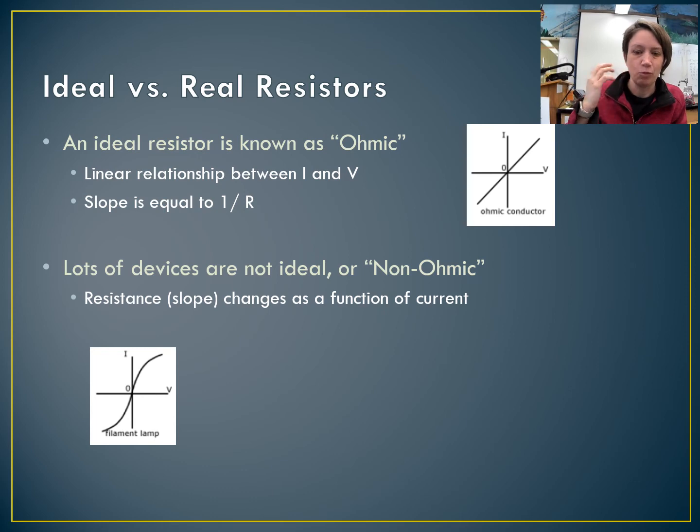So for a regular light bulb, if you try to attach an enormous voltage source, if you put too many batteries on your normal light bulb, the resistance actually goes up in that light bulb and the current starts to taper off. We start not increasing current as much. From a conceptual standpoint, this should kind of make sense, because functionally what happens is that light bulb gets really hot, the wire gets really hot, right?